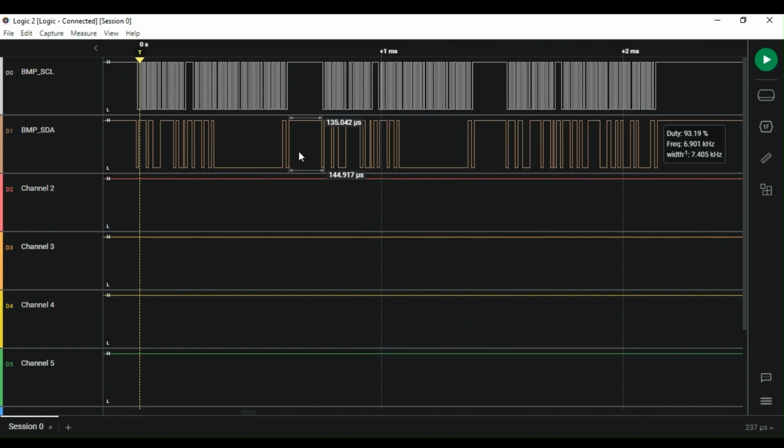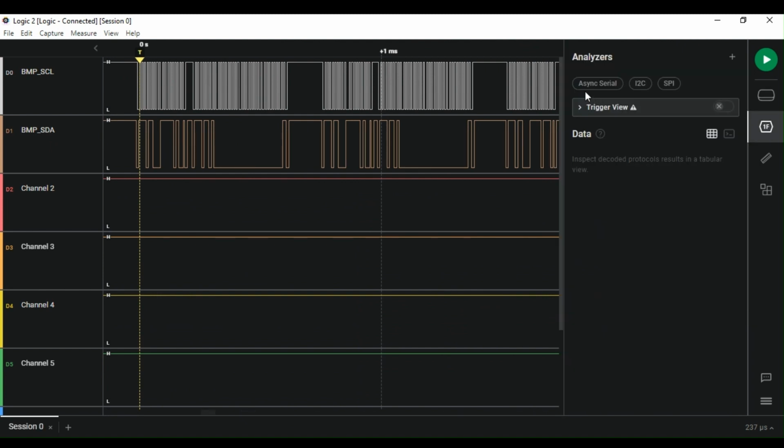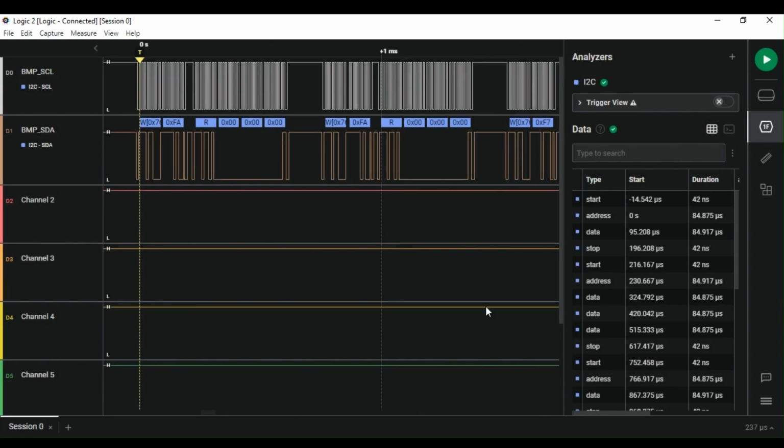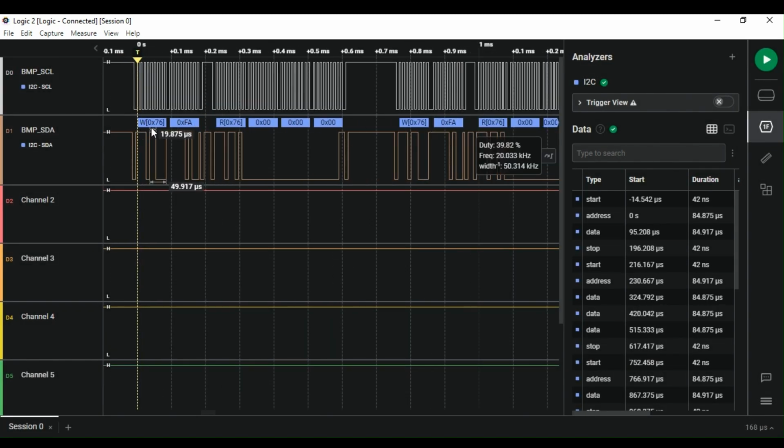It seems that the logic analyzer has recorded some transactions on the I2C bus. However, the abundance of ones and zeros is making it challenging to comprehend the situation. I wonder if the I2C extensions I installed earlier could be useful in this situation. I will check by utilizing the I2C extension functions. Indeed, that helps. I could now easily see the I2C address being driven by the UNO, the addresses of the registers read and the data bytes sent by the sensor.